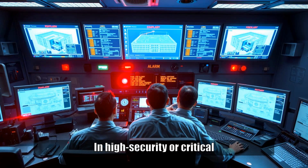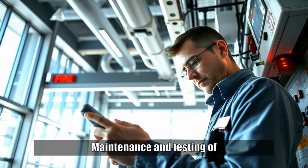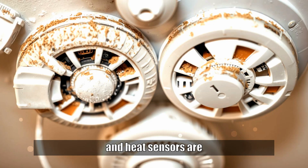In high-security or critical infrastructure environments, fire alarms may also trigger alerts to remote monitoring stations or emergency control rooms, where staff can coordinate evacuation or initiate contingency plans. Maintenance and testing of fire alarm systems are just as important as their initial installation. Components like smoke detectors and heat sensors are prone to dust, humidity, or mechanical wear, which can reduce their sensitivity or cause false alarms.